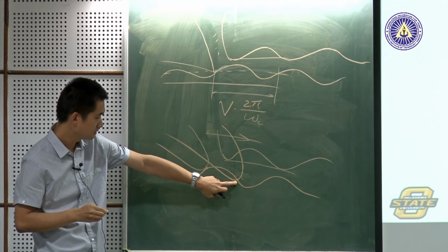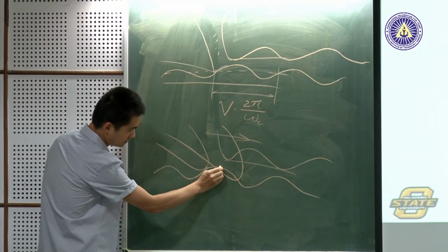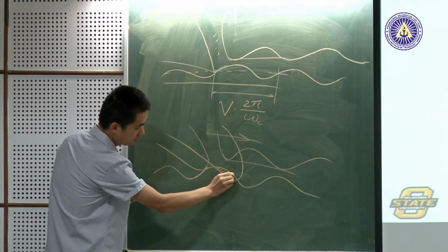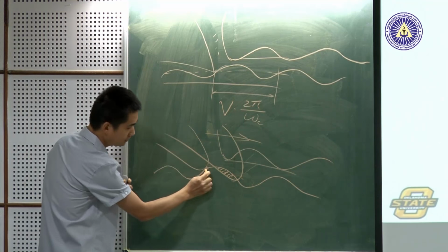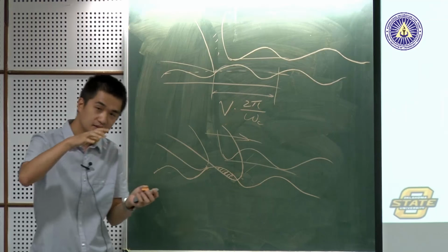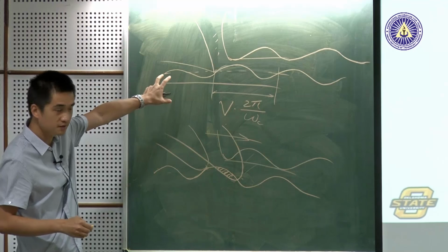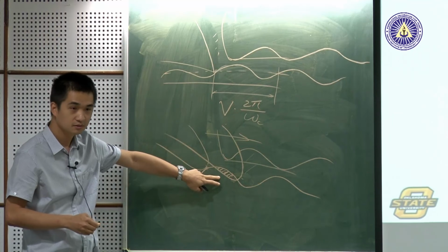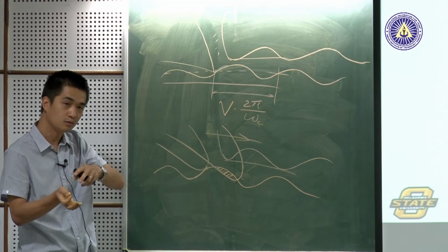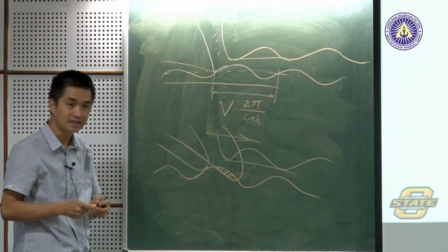So it not only removes the chip, but there's a huge contact between the flank face and this machined surface. The flank face and this bottom edge are trying to suppress the machined surface from the waves. As I explained previously, when there's material deformation, there's stress and strain, which converts into heat, called energy dissipation. From the dynamics point of view, why does it become like this?